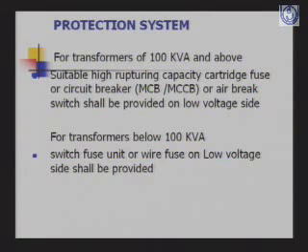So generally when you provide a wire fuse, you tend to put a higher size fuse. Then the transformer will definitely fail. The fuse wire should be of a size that it ruptures whenever there is some fault on the LT side. So one should ensure that and not put a very thick fuse that doesn't burn at all when there is a fault on the LT side.